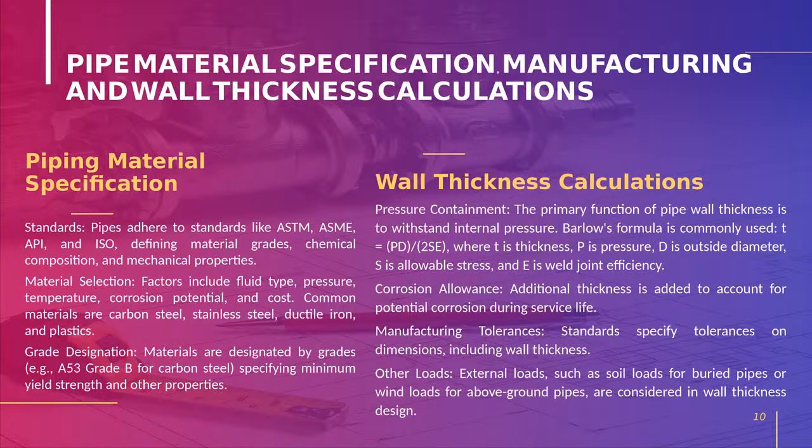Let's say we are going to deal with water, steam, oil. For water there will be a separate code in the PMS, and for a steam line, based on the temperature, we will name it differently. For example, if you are dealing with corrosive products, we will say SS. For steam lines, we will say carbon steel, CS. In steam itself there will be different temperatures and pressures, 6 bar and 60 bar also. In that case, for 6 bar we will say CS1, and for 60 bar we should use CS2.